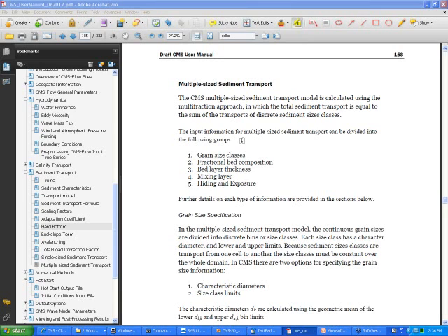The parameters that we use frequently for calibrating the sediment transport are morphology change, and if you have estimates in literature, for example, longshore sediment transport, you can compare model results to those values. But other than that, it's difficult.